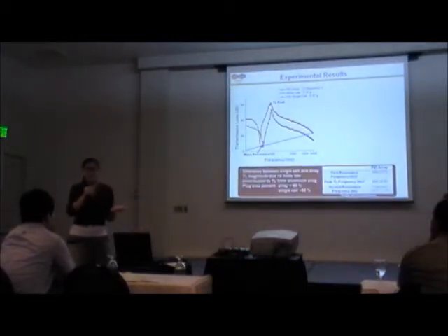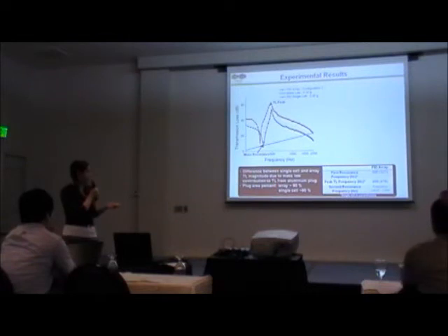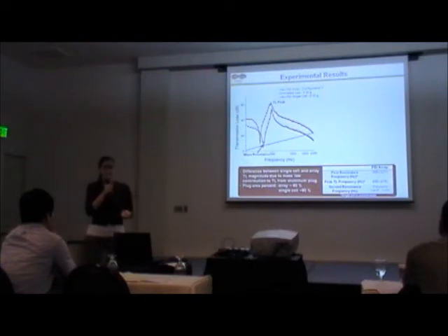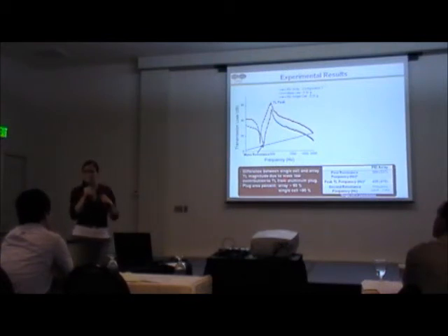However, there are some differences between these two peaks, and I'd like to talk about them a little bit. In terms of the magnitude of the transmission loss, this was attributed to the large amount of the incident area that is taken up by the adapter plug that we used. So in the case of the array, about 60% of the area of the tube was taken up by the plug, whereas in the square single cell, about 90% was taken up. And so that added mass from the aluminum plug is going to increase the overall transmission loss.